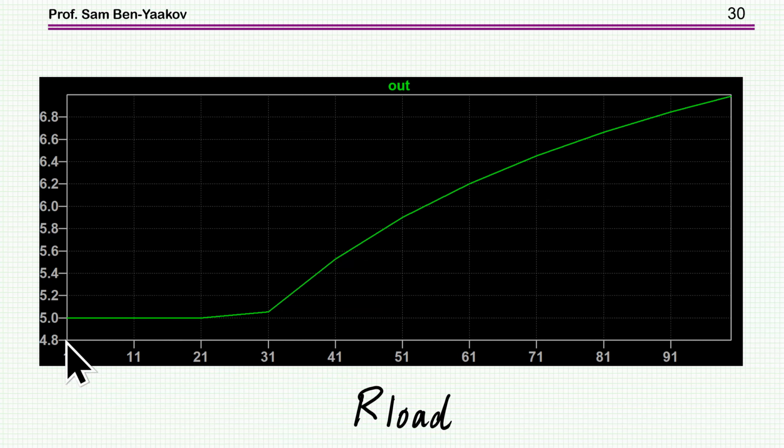And as we can see, up to say 21 approximately ohm, it is CCM, and the duty cycle is constant, independent of the load. Here, well, the resolution is not good enough, but here it's starting to change. And typically, as the load resistance goes up, the voltage goes up. So this operates very, very nicely.